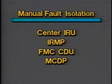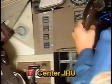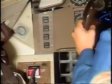You can also manually perform fault isolation using the center IRU, the ERMP, the FMC CDU, or the Maintenance Control Display Panel, or MCDP. You can substitute the center IRU for a failed left or right IRU to aid in fault isolation. To accomplish this, press the captain's or first officer's IRS alternate instrument source select switch.